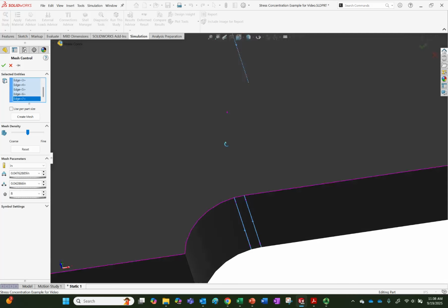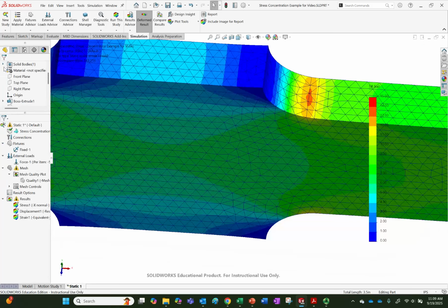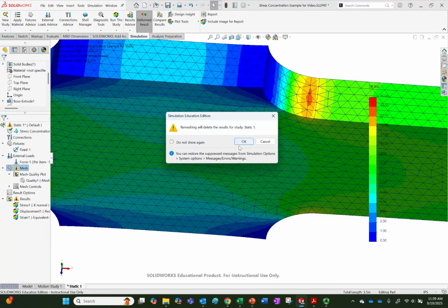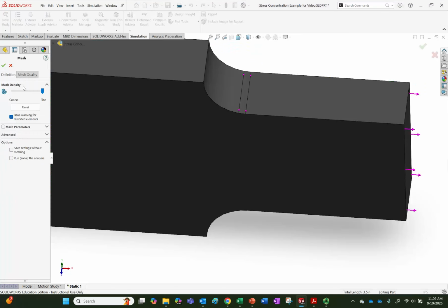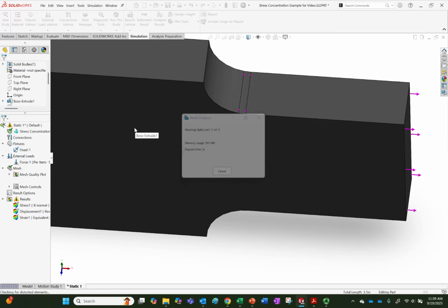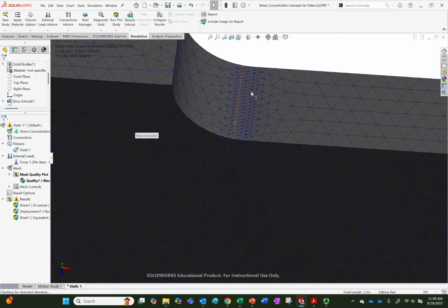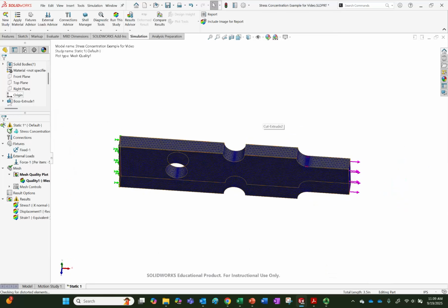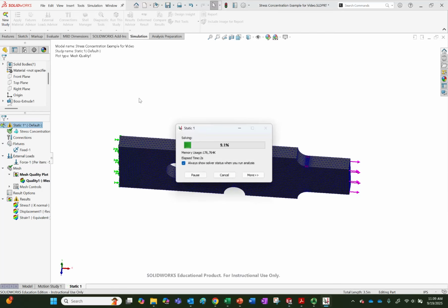Wouldn't hurt. All right, and now I'm just going to hit fine all the way across. So hopefully, when we create the mesh, we'll see more localized nodes in each of those spots, and run. We could have done this right from the very beginning, but it's just good practice to do a little mesh study.